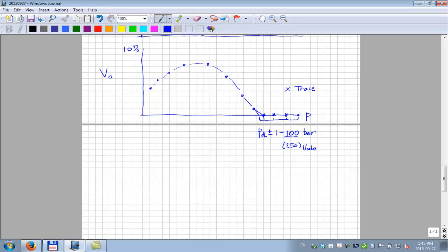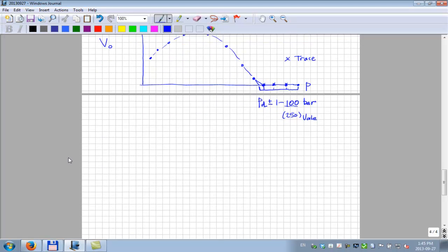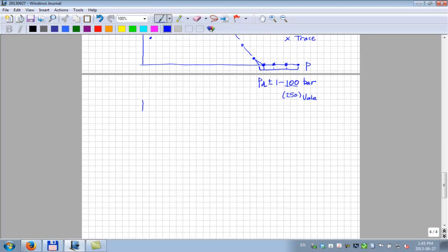It does have something to do with equilibrium, but everything has something to do with equilibrium. We want to know specifically, what do we know about phase equilibrium? The exercise we've been solving in class: what quantity says if a component prefers to be in the gas or the liquid phase? Yes, the K value. And we talked about that being greater than 1 or less than 1.